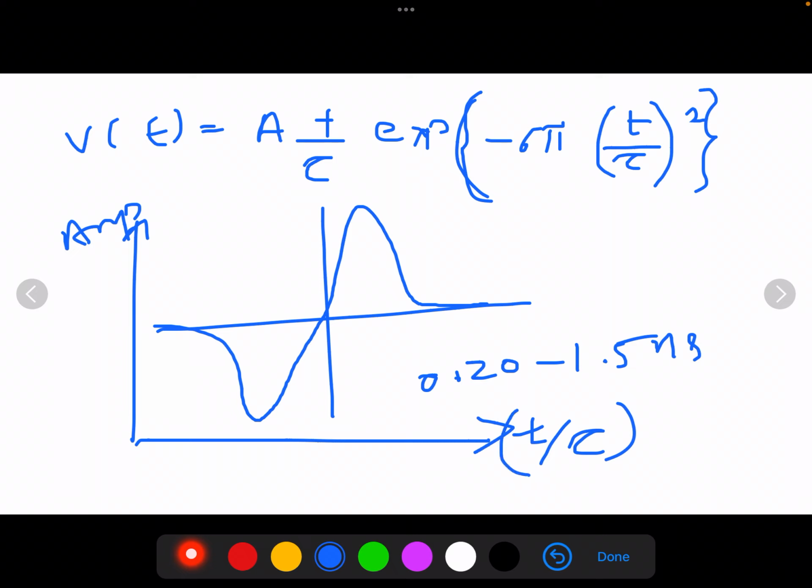So there are several methods for digitally modulating such an impulse wave. One method is the PPM. With this method, there is a nominal time separation Tp between the successive pulses. To transmit a binary 0, the pulse is transmitted slightly early, minus Tc.